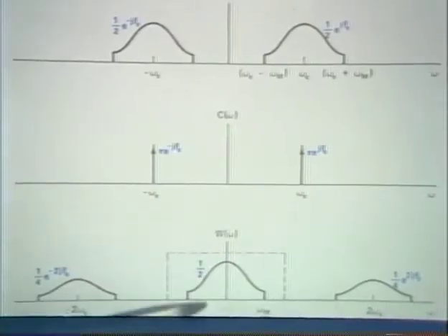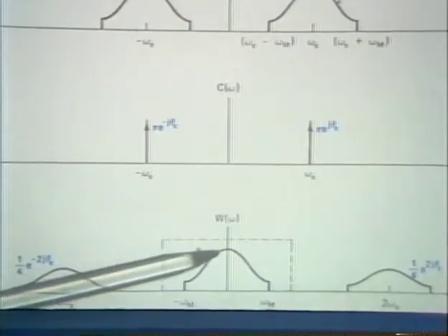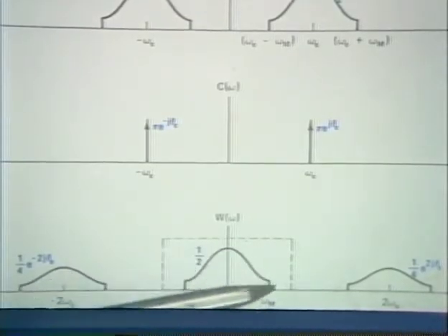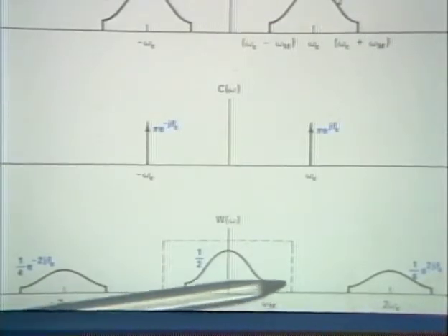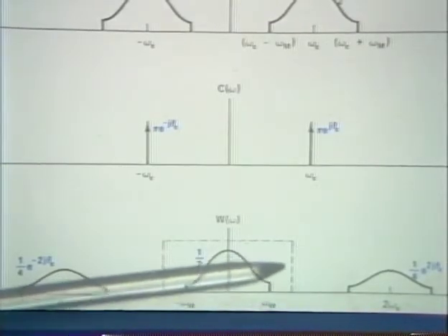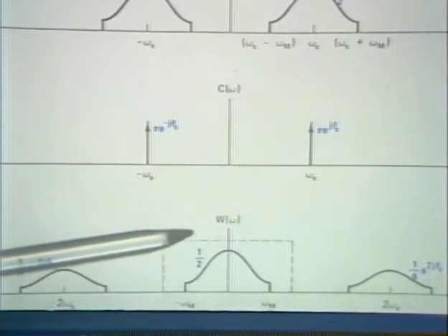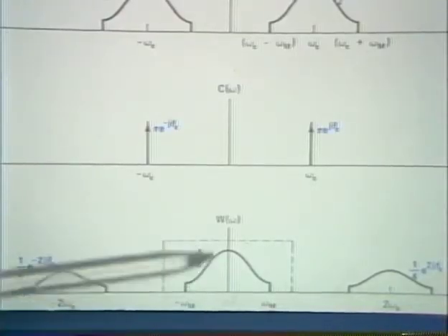And let me just draw your attention to the fact that because of the way the algebra works out, the amplitude of this replication of the spectrum is half what the original spectrum was, and that means that ideally to keep scale factors correct, we would choose the amplitude of this to be 2 to scale this back up to 1.